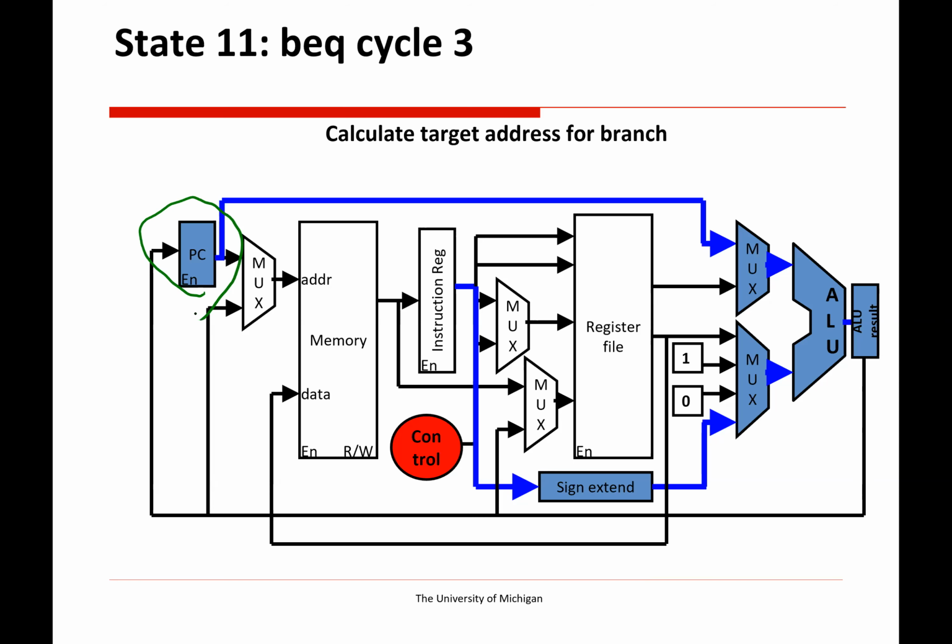So we were thinking ahead, and we designed the ISA around the microarchitecture, which is not always a great thing to do. Sometimes you get weird esoteric stuff, but sometimes you can get more efficient hardware that way. But anyways, this is storing PC plus 1. We're taking that value and we're going to add that to the offset.